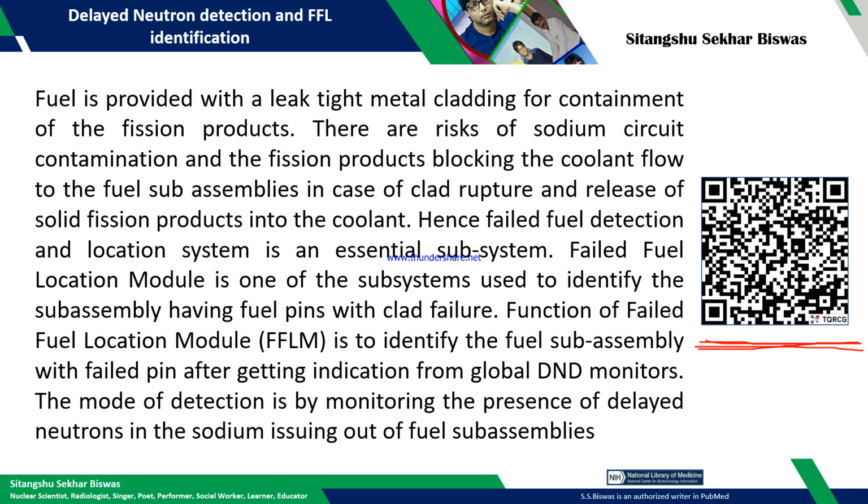So how to identify that? To identify that, one simple rotating driving mechanism is used. Using that mechanism, the coolant which is coming out from the subassembly is taken, and we just have to check whether delayed neutrons are present in that sodium flow issued from that particular subassembly.